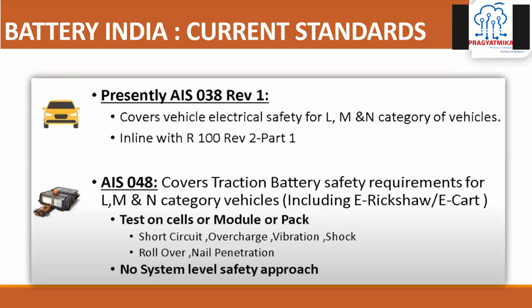So AIS 038 revision 1 is there for the L-category, that is your 2-wheeler and 4-wheeler and the higher category of vehicles, which is aligned to the European R100 standards. Whereas AIS 048 is there for your traction battery packs specifically.